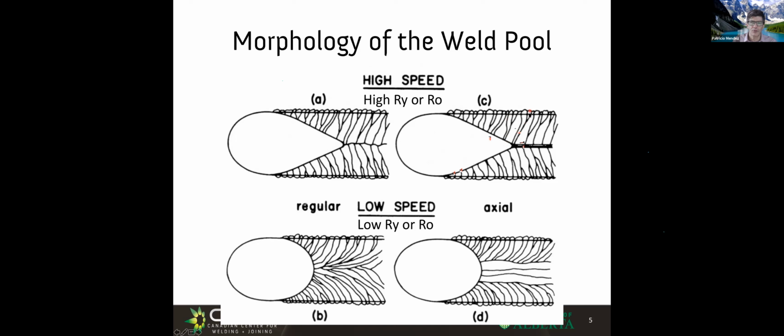In some cases, as it grows perpendicular, we have a problem because if you remember your phase transformations class, as you solidify things, you segregate the impurities to the front, right? As the two sides of the weld, the top side and the bottom side, start to solidify, both sides keep pushing and rejecting the impurities such as sulfur or phosphorus to the center. The center then might end up full of contamination, and that can cause hot cracking, can cause problems later down the road.